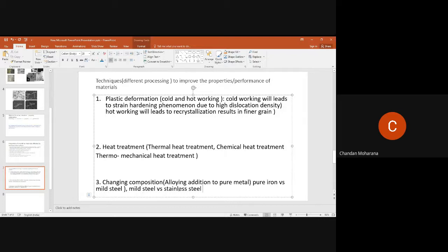So what kind of property will be enhanced? Corrosion resistance, chemical properties. Corrosion resistance will increase. It will not get easily corroded at high temperature also, right? But mild steel will easily corrode. Any other property? The strength will increase, the hardness will increase. Because of which kind of mechanism? Do you remember how the strength and hardness increase? The hint is: carbon is which kind of alloying element, and chromium and nickel are which kind of alloying element? Carbon is an interstitial alloying element. Very good.